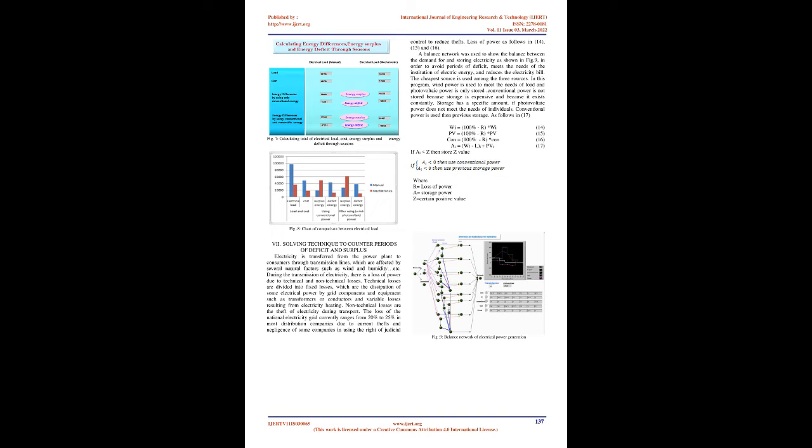V. Mechatronics. Based on intelligent agents science to control consumption, turning on when needed, sensors are used to convert signals from one energy domain to the electrical domain. A PIR motion sensor is used to sense motion or to detect whether a human has moved in or out of the sensor range. A DHT22 temperature sensor measures temperature, with a range from -40 to +125 degrees Celsius with ±0.5 degrees accuracy, and an HC-SR04 ultrasonic sensor determines the distance from the target object.